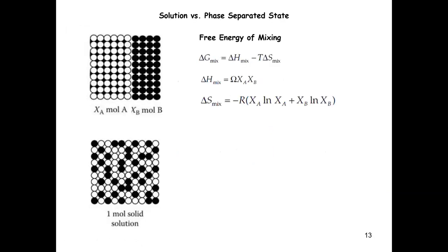So now let's do that in a more consistent way. We already have a lot of physical insights. Now let's make them more mathematically rigorous. So, again, let's go back to our long derivation. The whole point is that we want to get the free energy of mixing. But for the case of regular solution, we have to worry about this enthalpy of mixing, right? And we arrived at this very nice expression, and keep in mind that omega plays a key role in determining the physics of the system. But other than that, we express this enthalpy of mixing in terms of XA and XB.